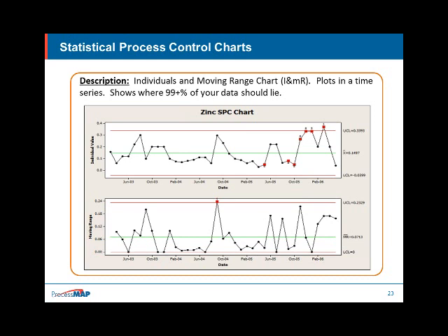The bottom red line tells us normally the lowest point that this process will run. Never usually runs below the red line. The top red line is the upper control limit that says we should never run higher than this line based upon our data, okay? So if you take a look at it, statistics will tell us that between the two red lines, our data should all fit between these two red lines 99.97% of the time.